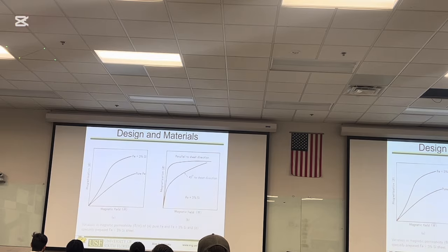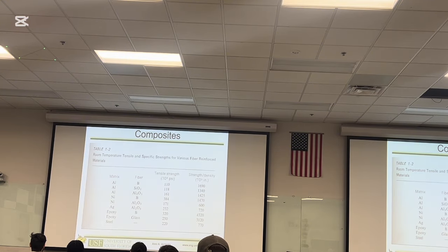We already had that graph of iron plus 3% silicon. It's a little bit of salt that you sprinkle on whatever you're going to cook tonight to make it more tasty. And then on top of that, you can change the rotation of the rolling. The rolling and processing creates deformation texture. All those grains get, have you ever played with silly putty? It gets stretched in a certain direction. So if you start rolling it, there's going to be deformation texture. And that's how the processing works this out.